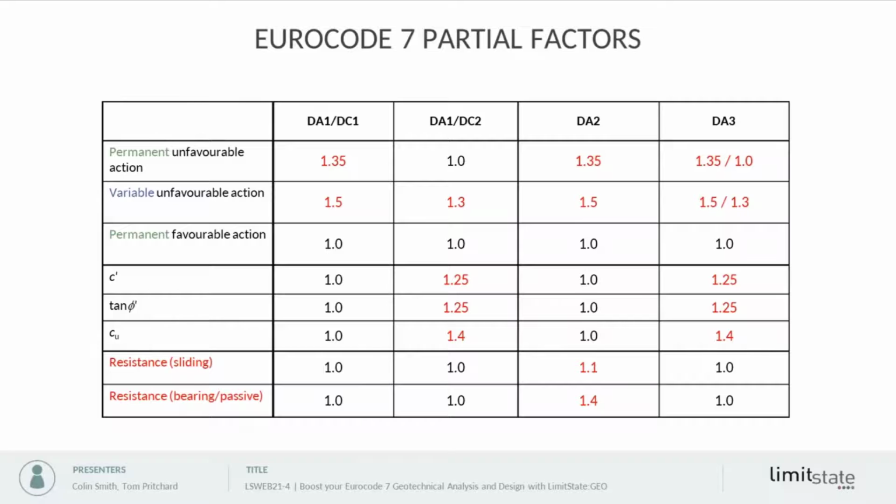So we have to analyze a very specific mechanism. Now we can do that with numerical methods, but we're not using the full power of a numerical method to try all possible failure mechanisms. We're having to force it to adopt a particular mechanism. So this kind of resistance factoring is very useful for hand calculations or closed form type solutions. But for general purpose numerical methods, it's not so useful.